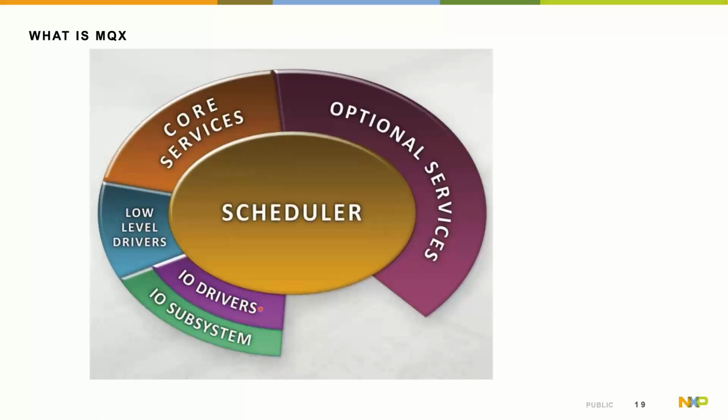And these I/O block drivers are for block-based interfaces. And on top of that is an I/O subsystem, which is unique to MQX, actually. So it's using a POSIX-like interface. So you use fopen, fread, fwrite to interface to all the block-based interfaces. And this, coupled with the fact that we've kept the API of MQX consistent throughout, makes it very, very easy for you to migrate from an older environment, either an older version of MQX and/or a different CPU, to a new environment like the RT1170.